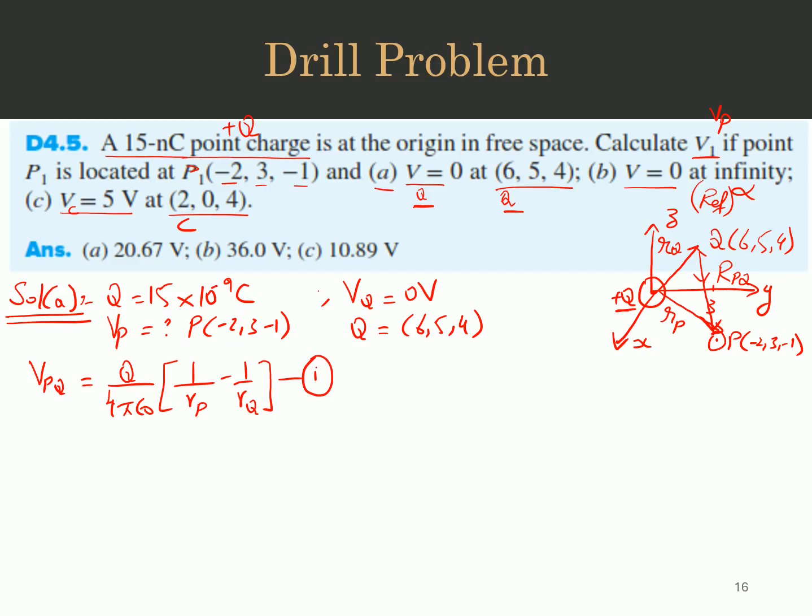The first thing is that we need to find V of P, and the equation has VPQ, which means that VPQ by default is equal to Vp minus Vq whenever the reference for Vp and Vq is ground. So this is the equation. This means that we can generate Vp from here when everything is figured out. So it will be Vpq plus Vq. This is equation number 2.